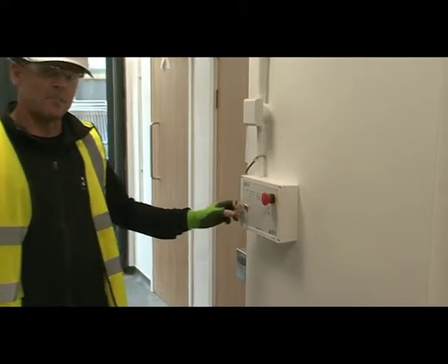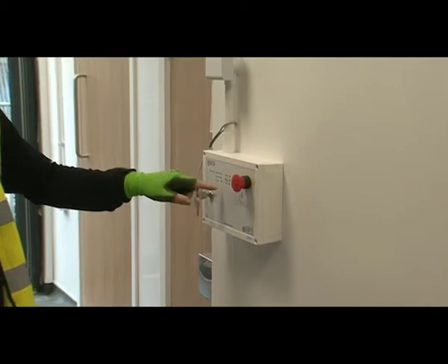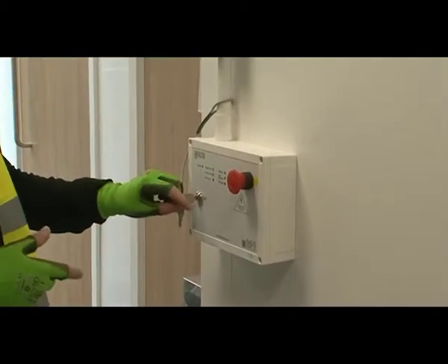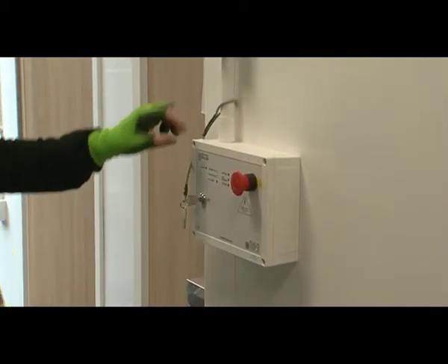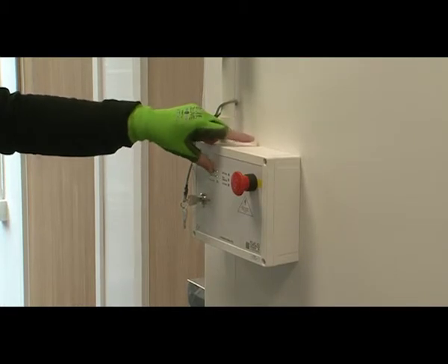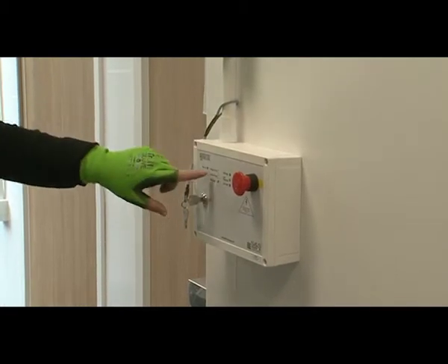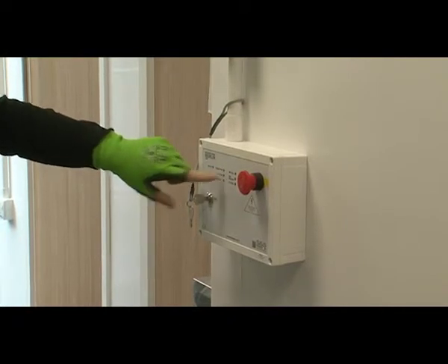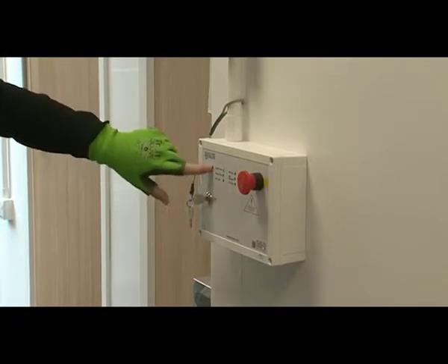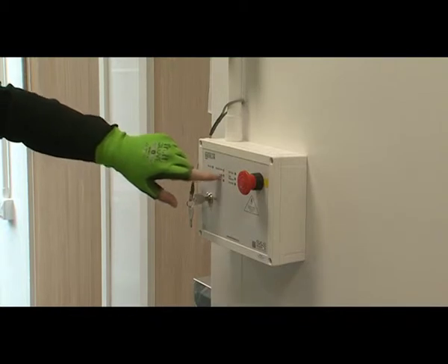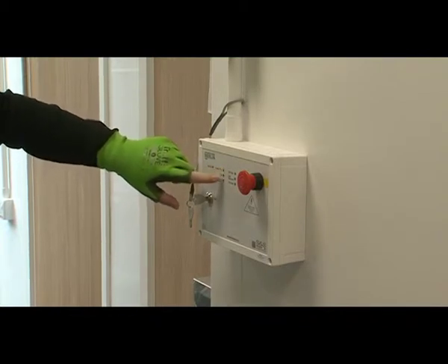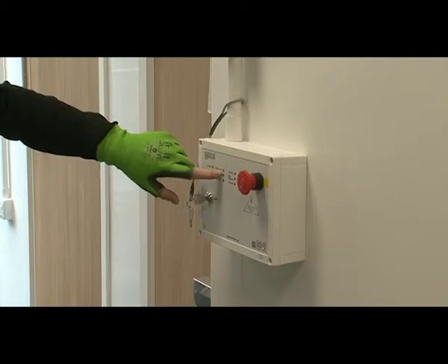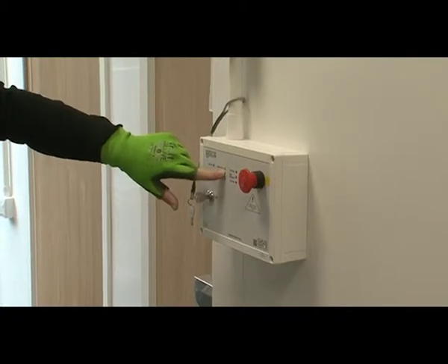What this does is then monitor the airflow from the air handling unit, which is supplied by contact from the BMS, and it looks for the supply and extract fan status, and it will make sure that we've got a fan flow before it allows gas through. At the moment the fans are off, so it won't allow the gas to be on. If the fans were on, these lights will be solid green. Because it's off, they give you a flashing green.